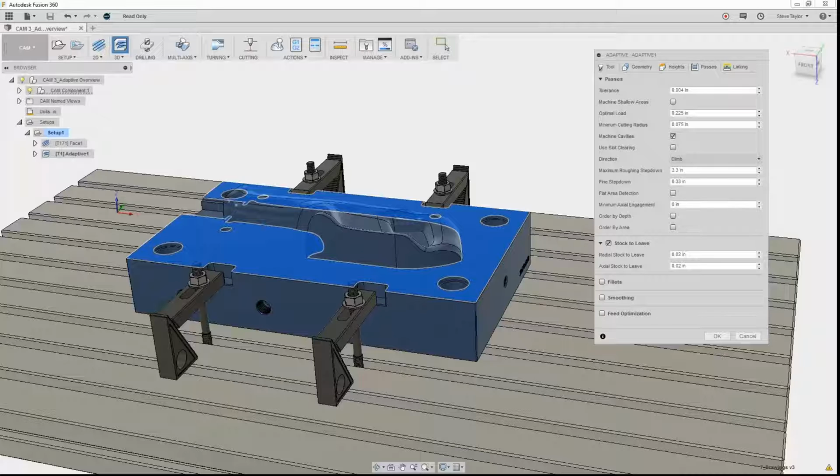This will also ensure that we are not just using the first quarter inch of the flute. When you're machining, sometimes if you're not careful, you might have a tool that's got a long flute length, and if you're only cutting all the time on the very bottom of that flute length, then that's where it's going to wear, and you're going to get uneven wear. If you then come to machine something later on down the line using that same tool and it's got uneven wear, you're not going to get the same accuracy or the same model that you want.